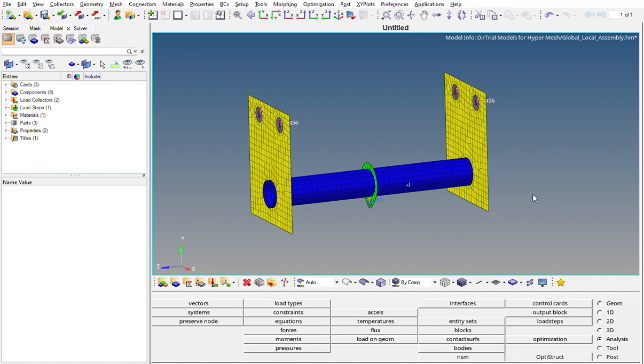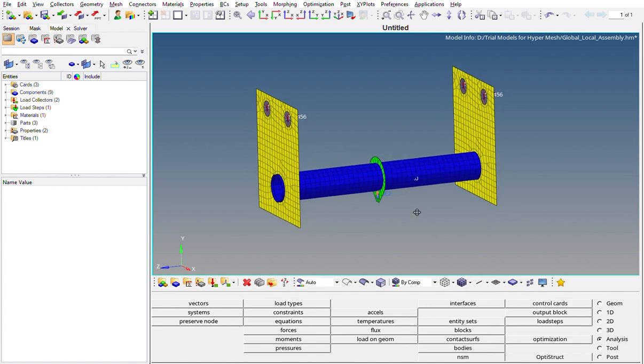So there might be certain n number of components, like 50, 60, 100, maybe thousands, who knows. So there are many components inside the aircraft, so they will also experience this loading. But we only have the loading at the assembly level. So we don't know what the loadings are at the component or sub-assembly level. So how do we derive it? For that, we have this global versus local analysis.